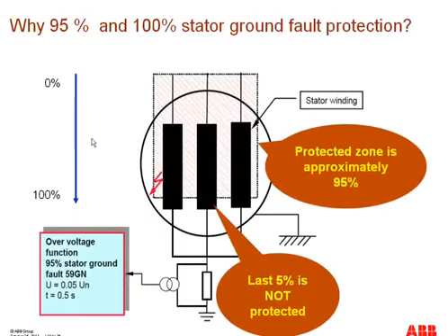So we normally hear that any single protection cannot cover the 100% stator ground fault. Maximum, it can cover only 95% of it. And this slide actually shows you the reason why we have to take special measures, in fact, to cover 100% stator ground faults.